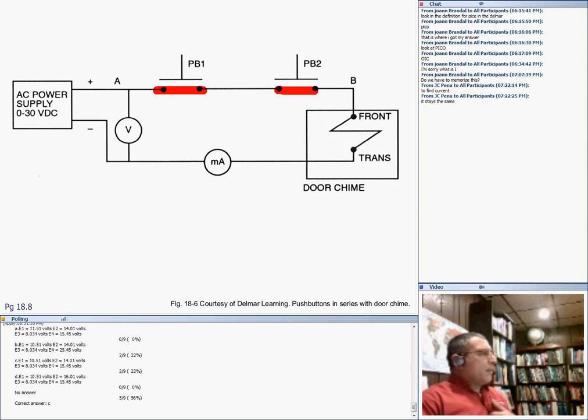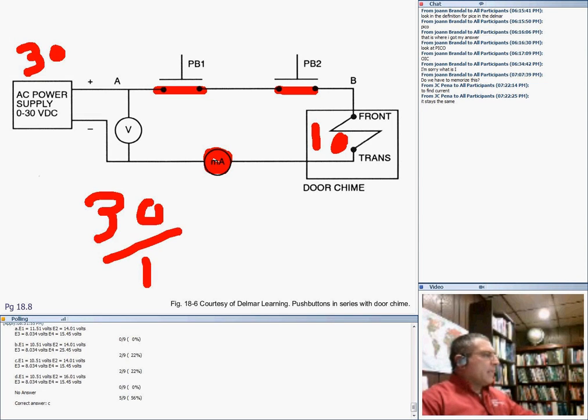And if I want to ask you, if this resistor was 10 and I set the voltage to 30, I'm asking you what would the meter read? You will say, Chad, no problem, that's the current. You take the 30, divide by 10, and that'll give me 3 amps. This is a milliamp meter, but say amps, this will read 3 amps.